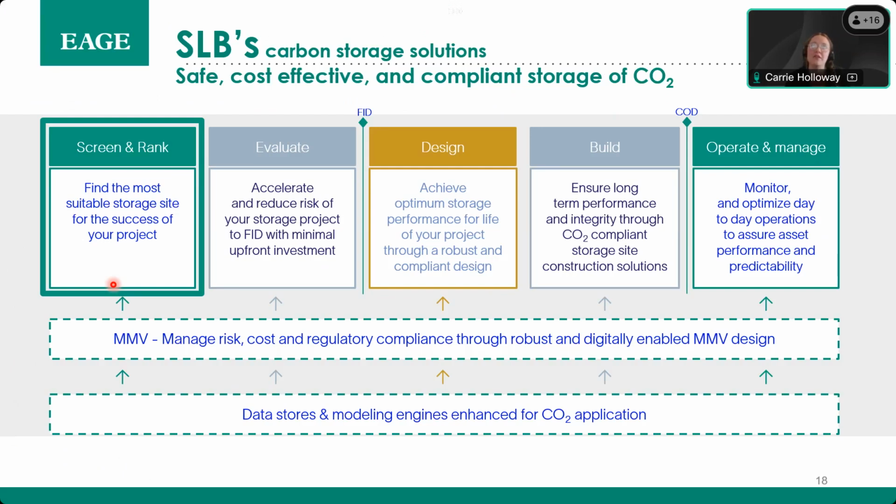So we need to run not only simulations, but also laboratory tests to understand at what pressure we can actually raise our reservoir to, and make sure that our injection scenario fits that. So we always want to be in a safe zone, so at least 90 or 80% below the fracture pressure on any of our faults or seals.